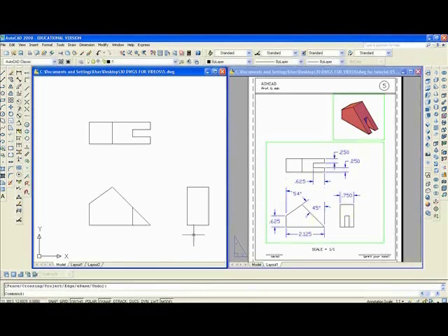Now we have to complete the right side view. And so we're going to O, enter. 0.25, enter. Here to here. And move that over that way. Then draw a line from this point here. Then fillet it with radius 0, that area.